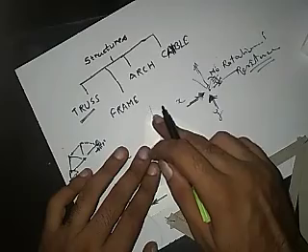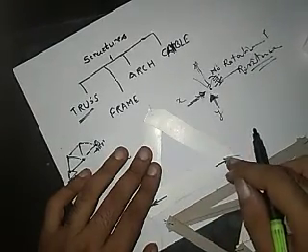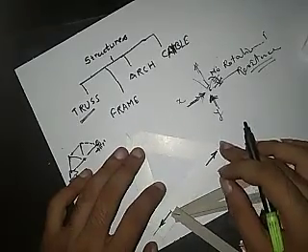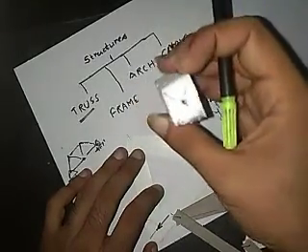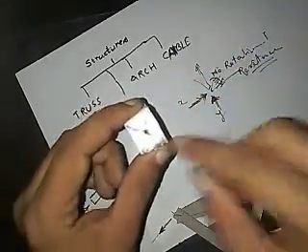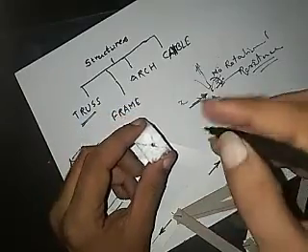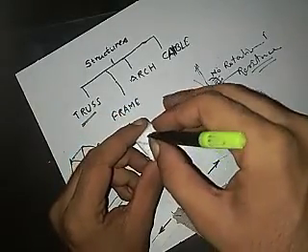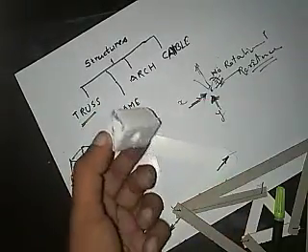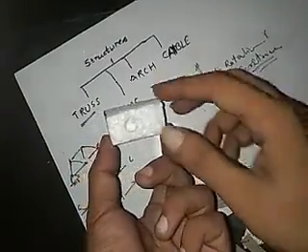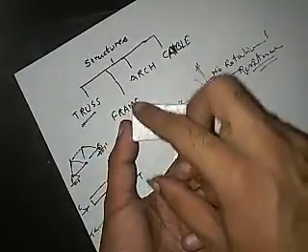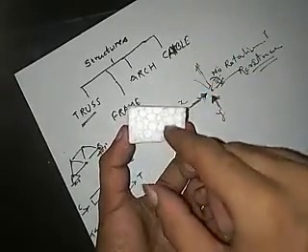The advantage of the first assumption is that these are pins. What is the second assumption? We assume that force is being transferred through the centroid. What it gives us is that if I am applying a load somewhere closer to the bottom section, then the force will be somewhere there, and if I apply a load force in that direction, you can observe there will be some bending in this cross section.